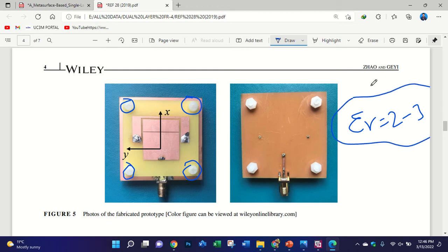In the case of my antenna for smartwatch application, when I embedded the antenna on the smartwatch strap, the strap is made of rubber, and my results may differ. That's why I do not prefer to use rubber; you can use foam or this screw.